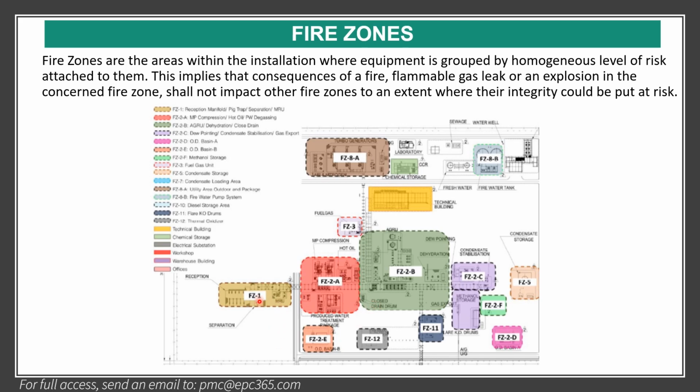For the deluge system, it is the same. It is for calculations of the fire water demand. If the deluge system here is initiated, we don't initiate the deluge system in this area. So that also helps to optimize the capacity of the fire water pump.